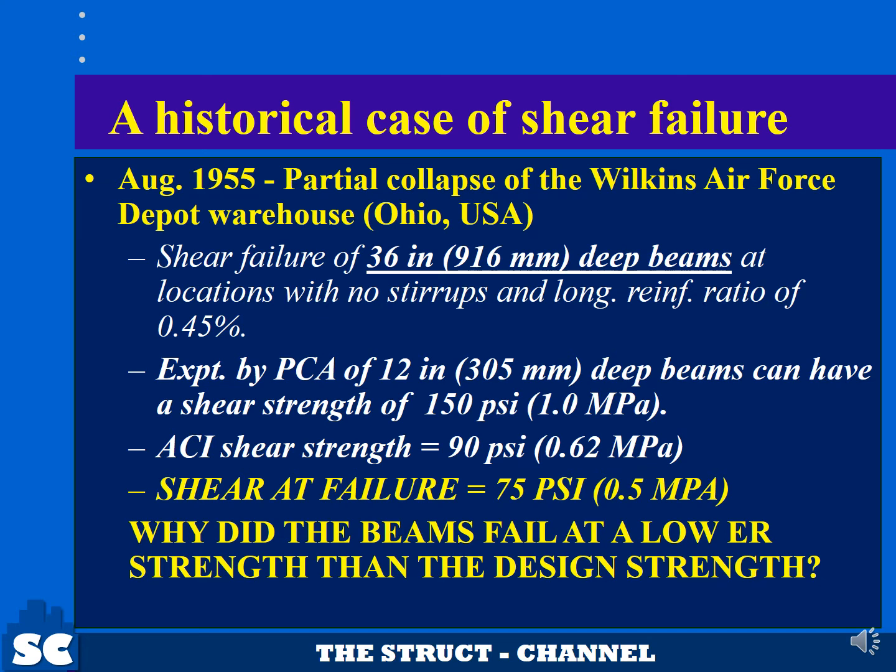There's a historical case about shear failure. In August 1955, there was a partial collapse of the Wilkins Air Force Depot warehouse in Ohio, USA. Shear failure of 36-inch deep beams, or about 916 millimeters, at locations with no stirrups and a longitudinal reinforcement ratio of 0.45%.